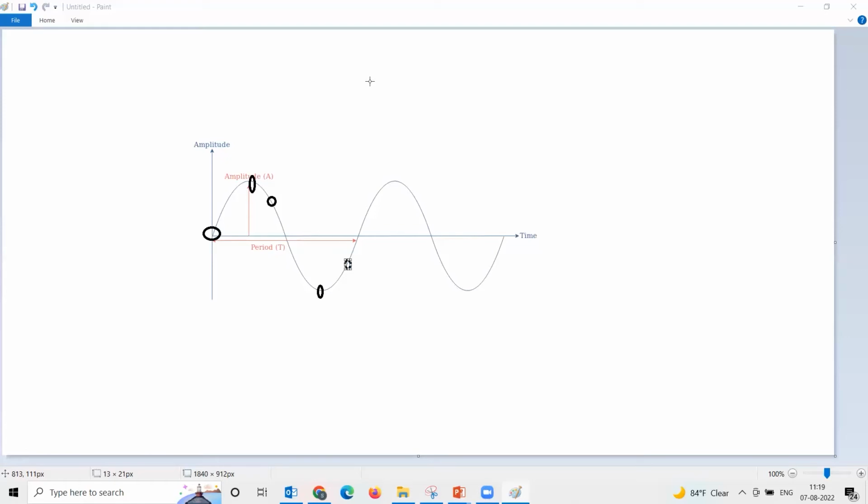So you should not really compare the results and say that the short circuit results performed by ETAP are wrong. You can raise such a question when the actual fault current at site exceeds the value predicted, or the value which is simulated in ETAP. You are simulating in ETAP, you are getting 28 kiloamps, but when there is a short circuit for the given system, in actual condition it reaches like 35 kiloamps, then again ETAP is not wrong.